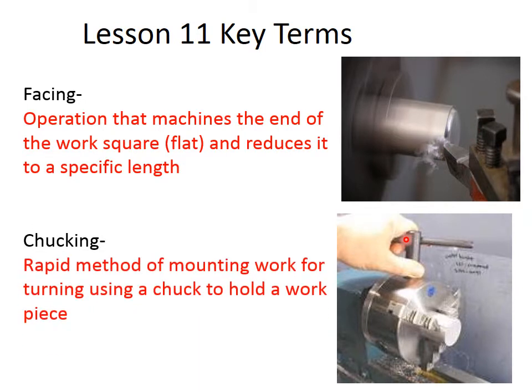Chucking: if you don't chuck your project correctly, it will fly out. This person up here is holding what's called the chuck key. The chuck key is really, really important. When you use your chuck key, you tighten your project down, and then you remove it immediately after use. You take this thing out immediately after you use it, and then you can start your machine. Do not ever start your machine with this in the chuck. Down here would be the project or whatever it is that you are going to turn.